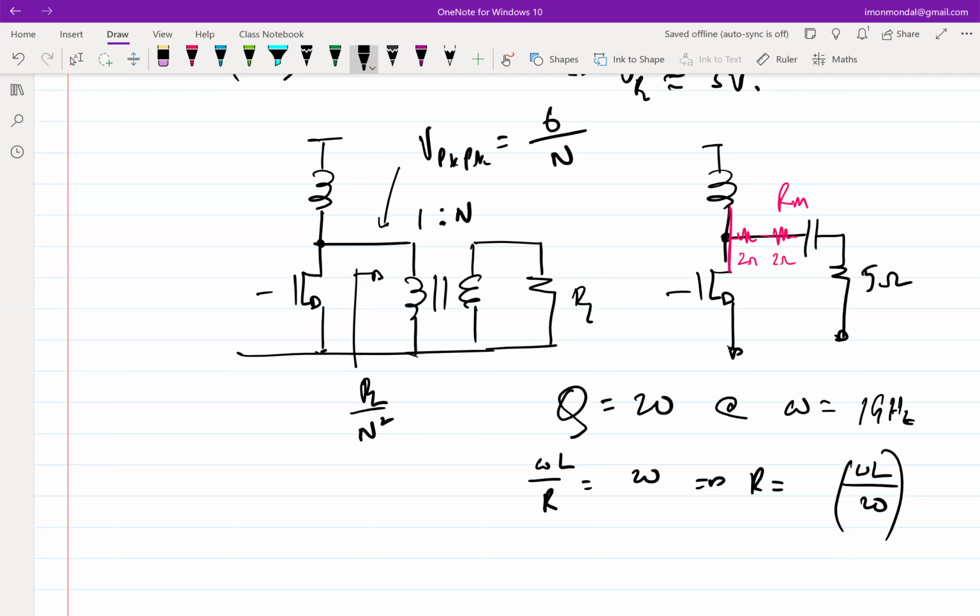Right. So right now your Q is essentially N. So if you recall, we had one lecture in which we talked about how we can split the matching network into multiple small matching networks and reduce the overall loss. Why? What is the root cause of loss in a matching network?